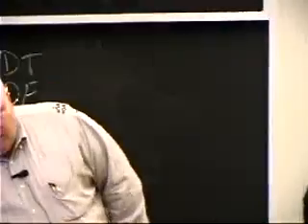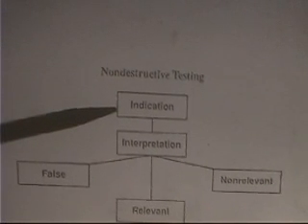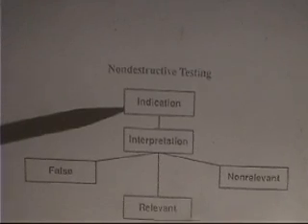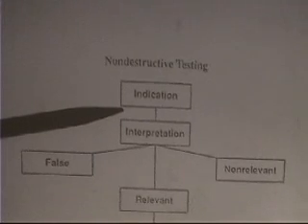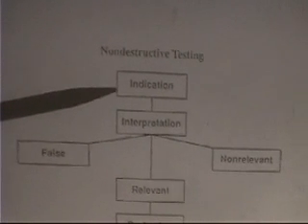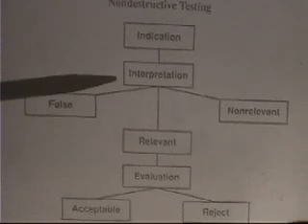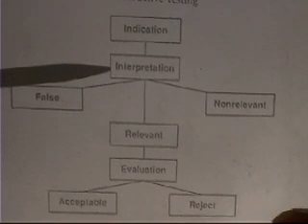But in any case, he calls this non-destructive testing, but in fact it's non-destructive evaluation. We don't call them flaws, we don't call them defects, we call them indications. There's something that showed up on the detector. We don't know what it is, and that's the great mystery, and that's what all the engineers will debate. And now the evaluation means that you have to interpret what that indication is.